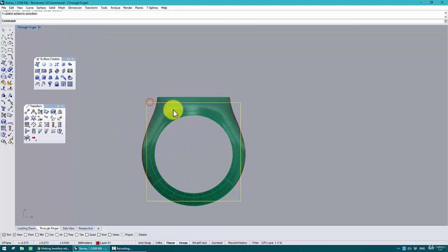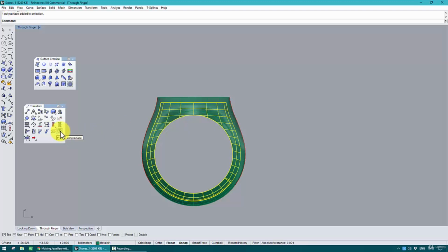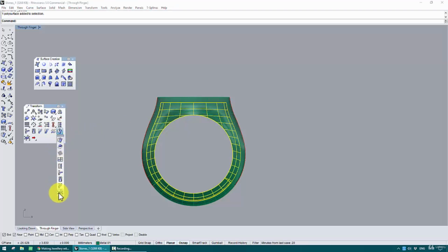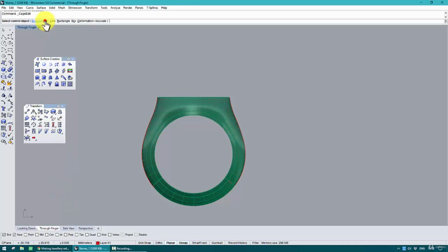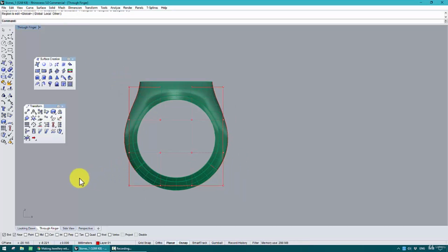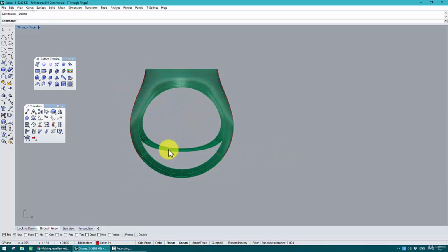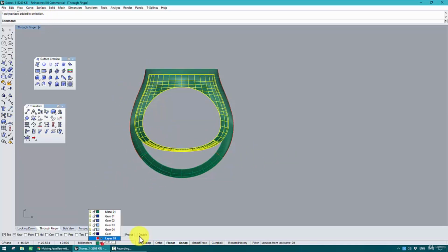I'll do it again. We select the object that we want to edit, we open this menu, we open this menu, so left click here, bounding box on the command line, enter, make sure you have 4, 4 and 4 on each axis. These are the edit points on each axis, so 4, 4 and 4, enter and enter. Then we just need to select the ones at the bottom and move up to here.